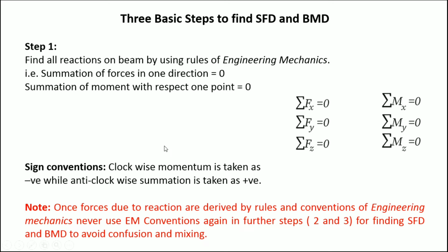And why are we finding the reaction forces? Because these forces are necessary for drawing the shear force diagram and bending moment diagram. So always keep in mind this note: once the reaction forces are derived by the rules and conventions of engineering mechanics, never use these engineering mechanics conventions again in further steps number 2 and 3, which are used for finding SFD and BMD, to avoid confusion and mixing. That means don't mix these rules with the second step or with the third step.